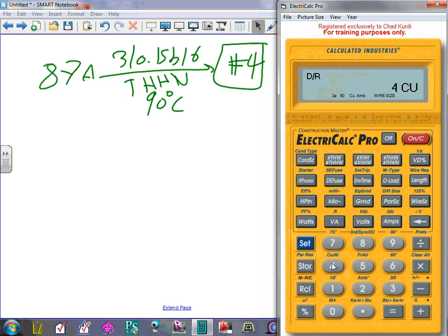Set copper, set aluminum. So you can switch right there when you do rate. You do rate based on aluminum, based on copper, you name it. Now, when one of you guys sit for your master exam, say the conductors are outside,